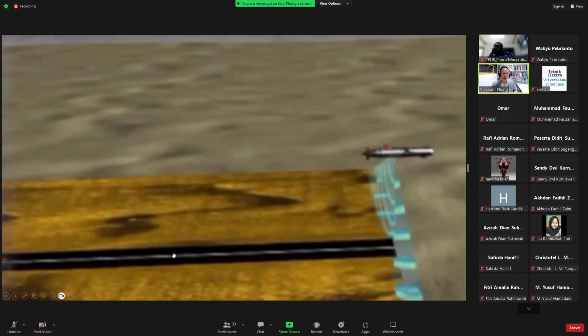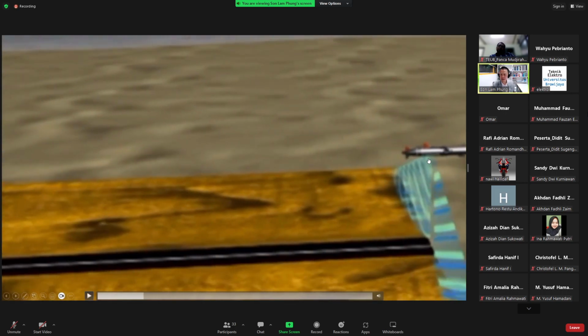So how is a sonar image formed? This video illustrates how the AUV travels. When the AUV travels, it will send a beam of ultrasonic signal, ultrasound. So the ultrasound, when it hits the seabed floor or any target, will be reflected back. And then by collecting the reflected signal, this sonar will form an image of the seabed floor line by line.